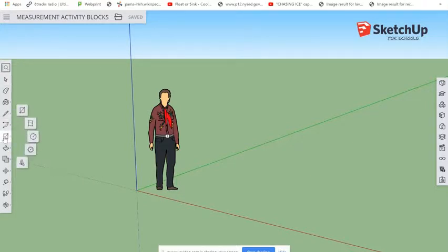I'm going to come over here and click the rectangle tool. So again, I click the rectangle tool, I click and drag the area that I want to make the rectangle. Now obviously that's way too big. As I look down here on the bottom, it says 731.82 by 1540, so that's way too big. I want mine to be, I think it was 21.2 by 30. Okay, so I'm going to type in 21.2 comma 30 and click enter, and bam, there it is. It's much smaller.